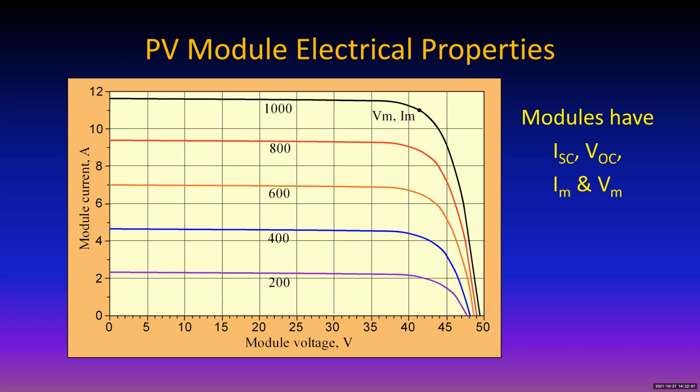The voltage, on the other hand, doesn't behave at all like that. In fact, it behaves according to the logarithm of the intensity of the sunlight. So even when the sun is not shining very brightly, there can be a lot of voltage across the terminals of a module, so you have to be a little careful with the module terminals. Of course, the leads on the modules have shielded connectors, so it's pretty difficult to get a shock from them. It's about like getting a shock from a light switch.